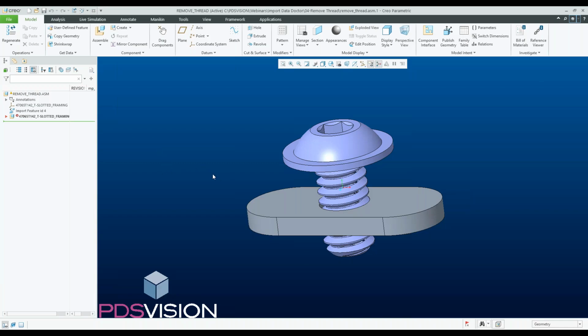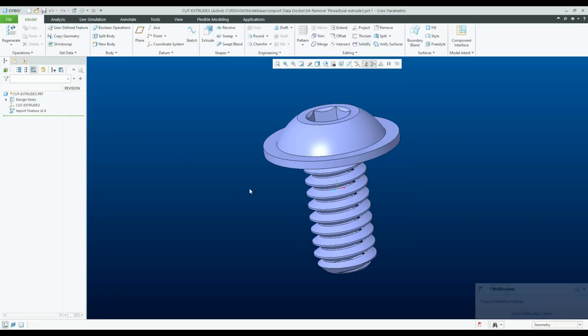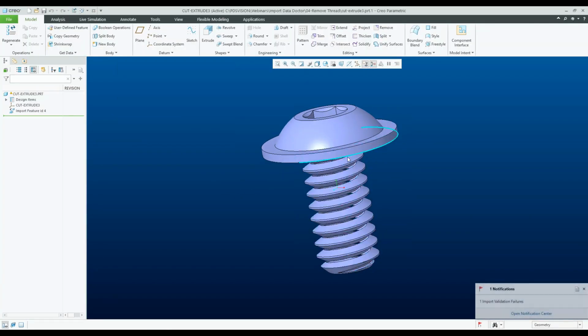It's because if I have a big assembly and I use hardware with a thread there, every surface will need to be regenerated, and this will create a big issue in a big assembly. Your big assembly will regenerate very slowly because even if the thread is not visible, it will take a long time for the system to go through all surfaces to regenerate.